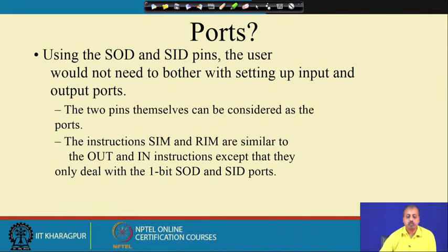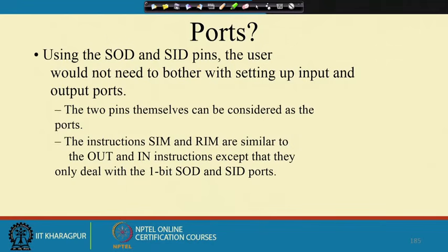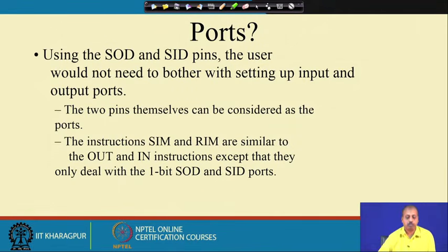Using these SOD and SID pins, the user would not need to bother about setting up input and output ports, because only a single line connection is there, and these two pins themselves can be considered as ports. So, you can connect it to some other device that supports this serial transmission. The instructions SIM and RIM are similar to the OUT and IN instructions, except that they only deal with 1 bit serial output data and serial input data ports. So, we can think of SIM and RIM as equivalent to 1 bit operations.